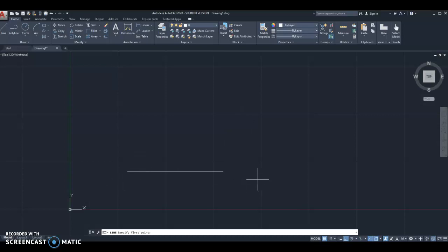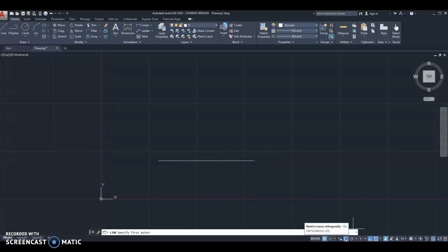I'll save diagonal lines for another video. So hope that helps get you started. As I said, the first homework assignment I think can be completely done by vertical and horizontal lines. So I would recommend having ortho mode or polar tracking turned on, just choosing your starting point and then indicating the direction you want to go with your cursor and typing in the length of the line with the keyboard.